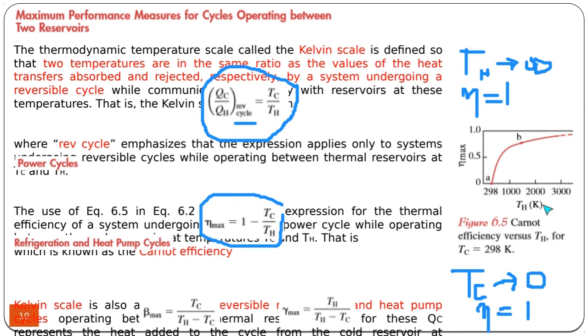For instance, for a power plant or internal combustion engine, because of the material considerations, you cannot increase the temperature higher than 2000 Celsius or 2500 Celsius at most, maybe. So because of the material considerations, you have to limit the temperatures below some temperature, for instance, somewhere around here, so that the maximum efficiency for a Carnot system is 60% or maybe 70%.